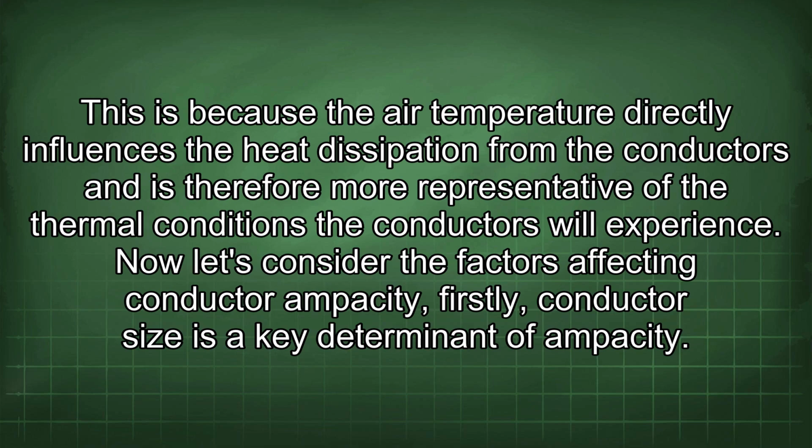For ampacity calculations, the ambient temperature is the more relevant factor. This is because the air temperature directly influences the heat dissipation from the conductors and is therefore more representative of the thermal conditions the conductors will experience. Now let's consider the factors affecting conductor ampacity.